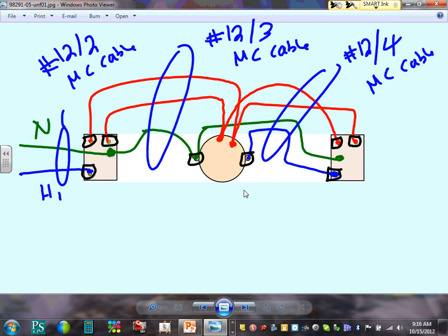Inside the box, there's a box here. It has to be a box. They just connect them with a wire nut, push them inside the box. They're not landing on the terminal of the light. Terminals of light. Any questions, guys, about this? Yes, Aaron? One more time. I was just saying, they're just going through the switches. Yeah, they are carrying the travelers. They're tying the travelers together. But this is actual physical mechanical wiring. That's how you do it.